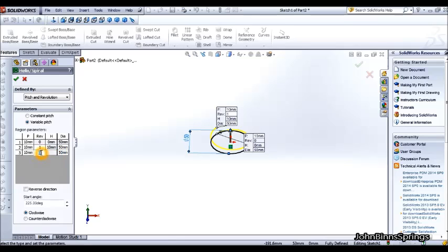So what I'm going to do here, I'm going to put 9.5, so that will jump from 1 revolution to 9.5 revolutions. And then here I'm going to enter in what I want the top dimension to be of the top circle. I want it to be 35 mm, and as you can see the preview shows the actual spring curving in, and all the calculations are done so it's all even through the whole spring.